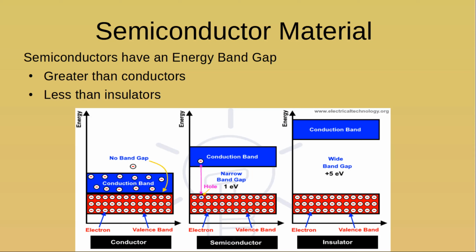When we have a semiconductor, there's a band gap. When the conduction band of energy and the valence band are separated by approximately an electron volt. And that's why in the semiconductor material, we'll talk about in a little bit, you see a bias voltage required for a diode to conduct through a p-n junction. That's where that comes from, is that band gap.